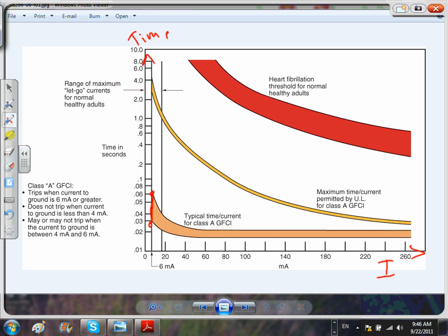And this is the tripping mechanism for my GFCI. And I know Christian can argue with me, but supposedly, if you go from here, here's 180 milliamps, up to here, and you cross-reference it, that will get you, say, 1.5 seconds. Within 1.5 seconds, they're going to join Jesus Christ, directly from here. If that's your destination. If you have another destination, you can join that destination too. Supposedly, based on statistics. You know what I mean?